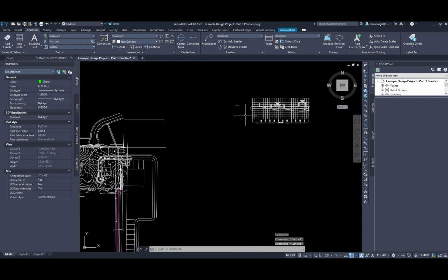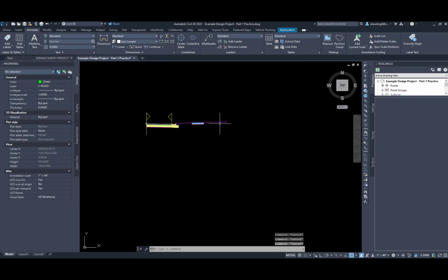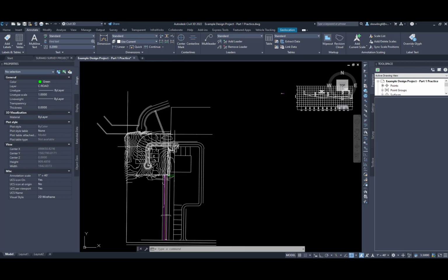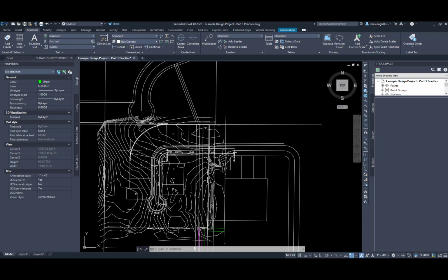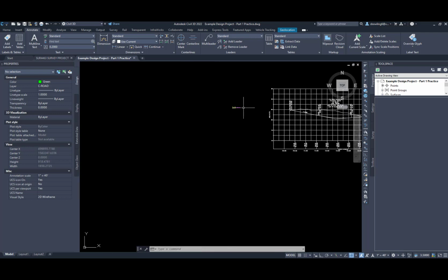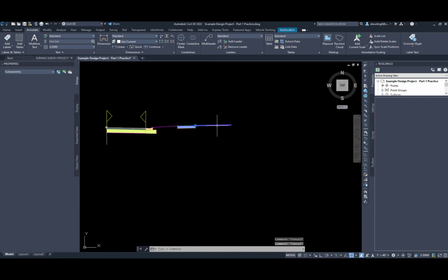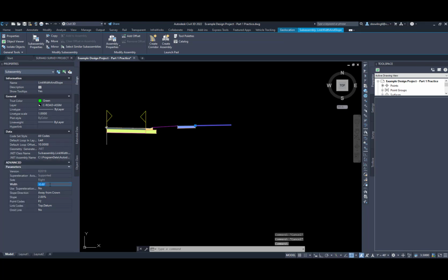So I'm going to come back over here, and I want to be able to pick up at least the backs of the lots. When you're working on corridors or an assembly on a curve, you'll actually want to extend part of that because of triangulation, calculation of surface areas. Again, I can explain that later if anybody wants to know. So I'm going to make that length 105. I'm just going to go a little bit past the length.